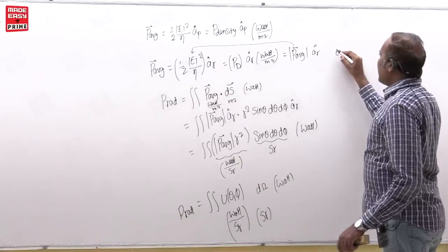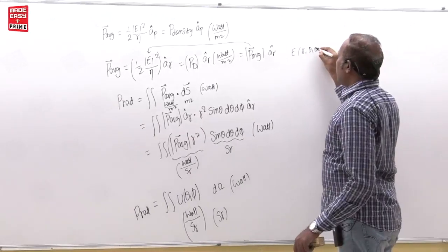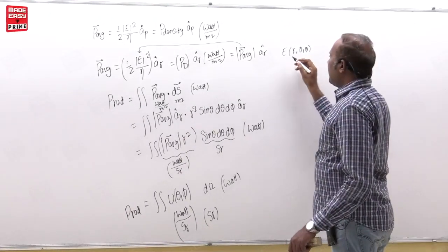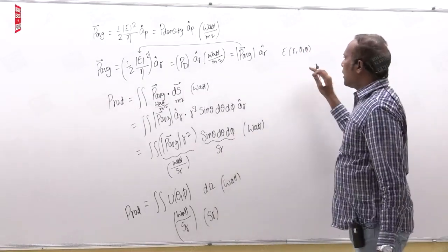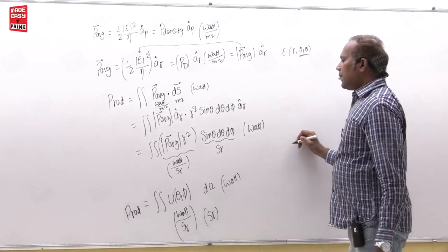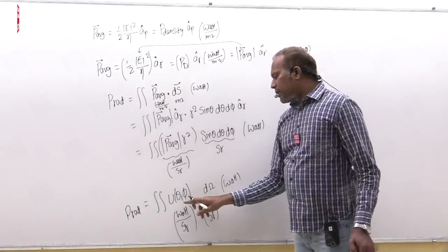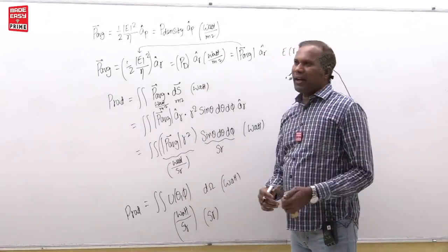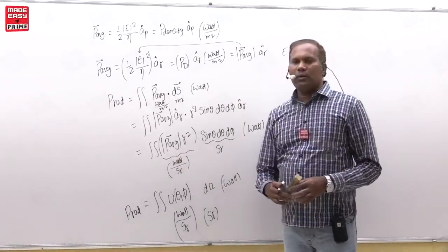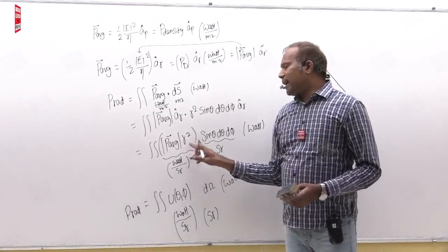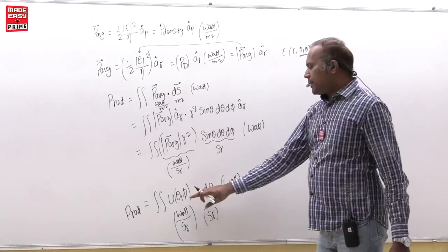If you solve the electric field in the spherical system, it is a function of r, theta, phi; electric field square multiplied with r square, the r term is gone, and the remaining terms are theta and phi. That is why it is symbolized like this. So radiation intensity is a function of theta and phi only.